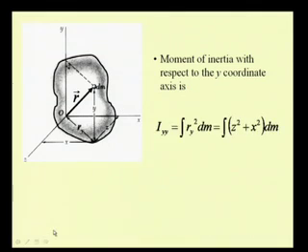So, we have the second moment of this entire rigid body with respect to the y axis, I yy, which is equal to the integration of the distance of this particle from the y axis, which is this distance, which let me call the projection of this vector on the x z plane.